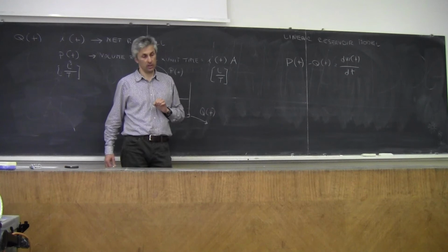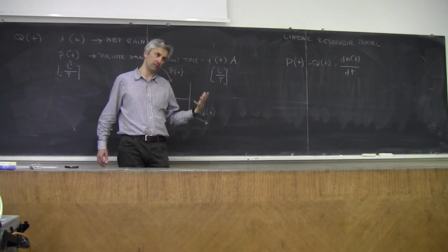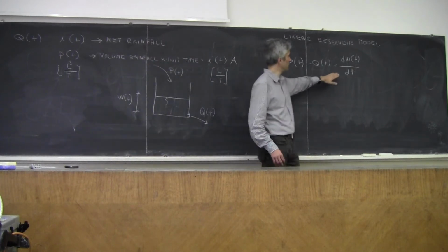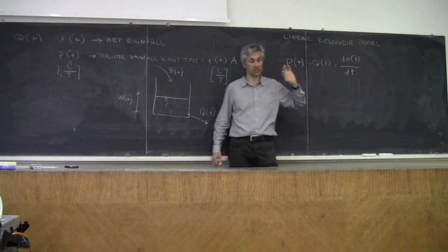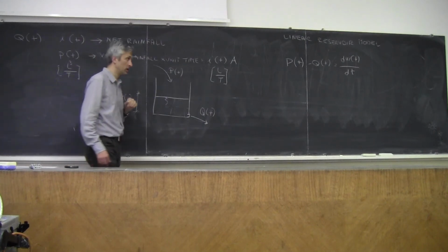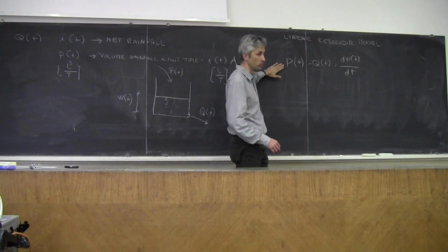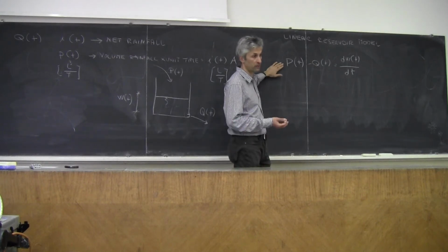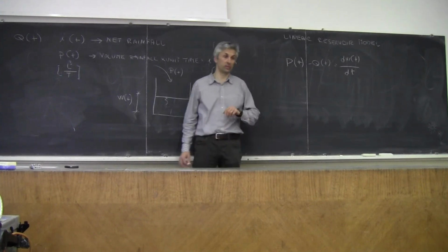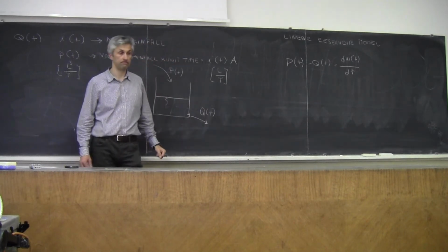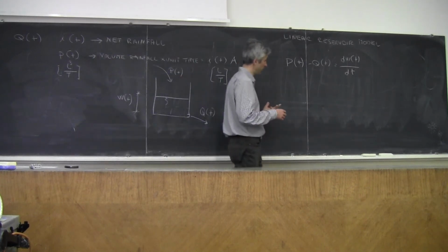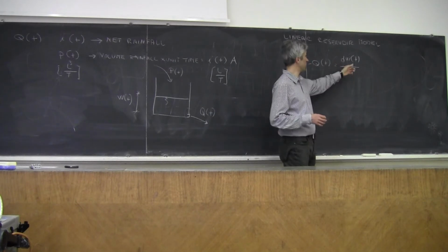But be careful. This is a mathematical equation which is physically based, where I introduced a state variable, which is the volume of water that is stored in the catchment. This is a state variable, which is unknown. Therefore, in this equation, you have one known variable, which is rainfall, but two unknowns. So it's an equation that you can't solve by itself. You need to couple it with another equation, a second equation explaining W(t).